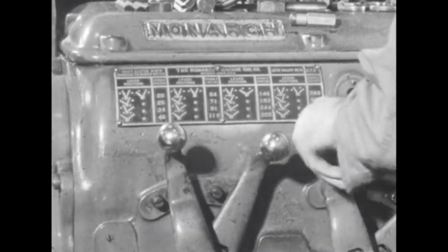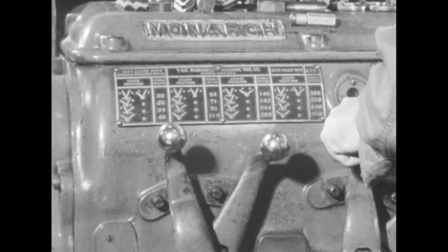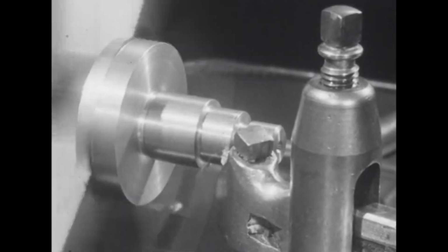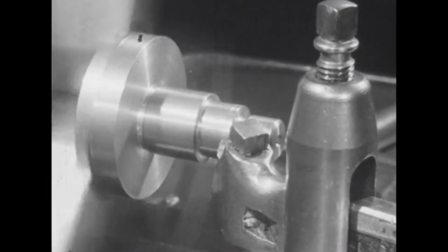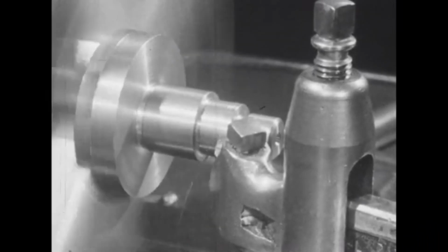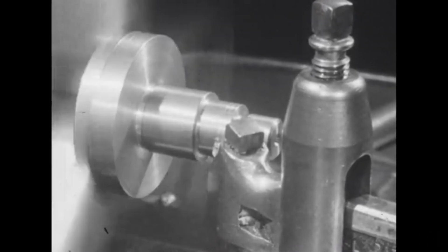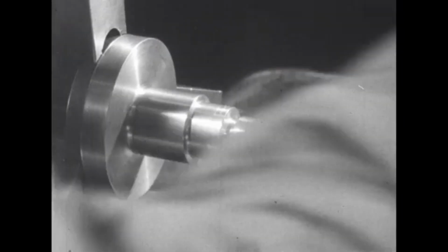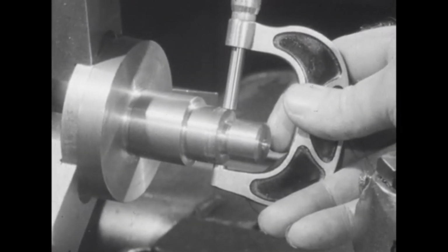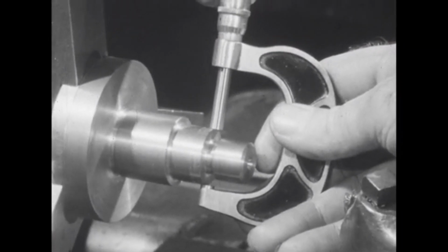The finish cut, which aims at the specified 1-inch diameter, is now made. The more critical the dimension, the oftener the lathe must be stopped for checking the measurement. Such stoppages take time, and therefore cost money. The engineer must know when the desired result justifies such cost.